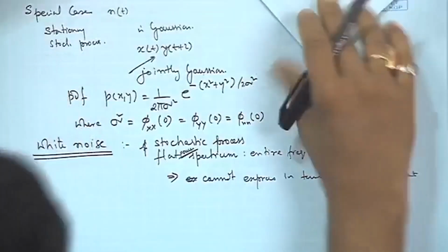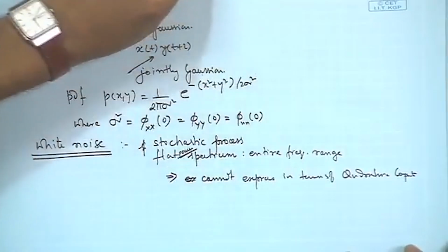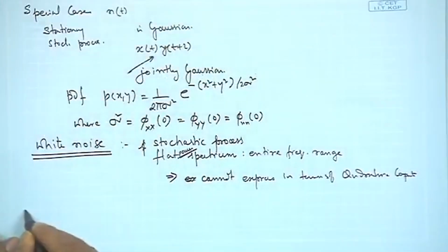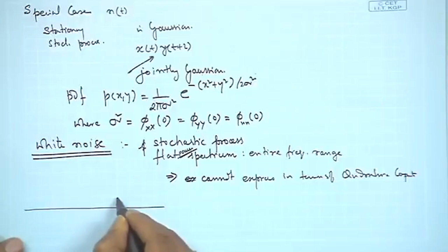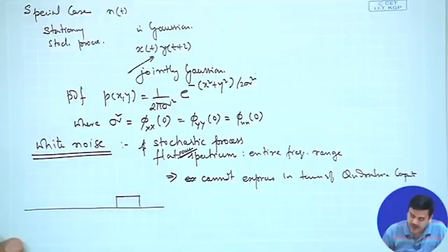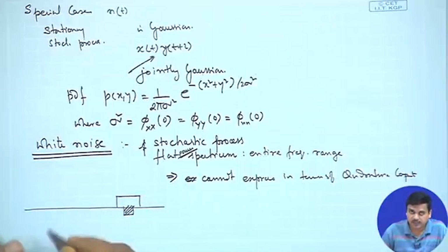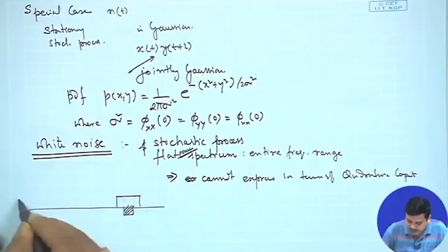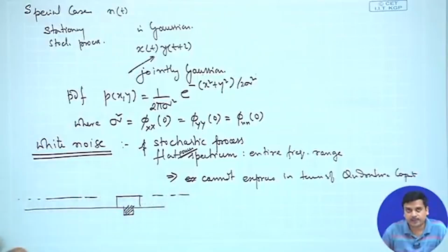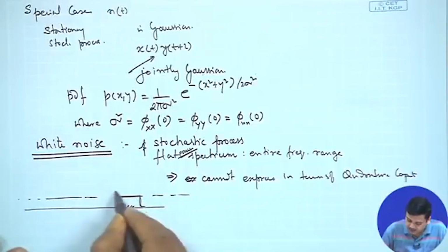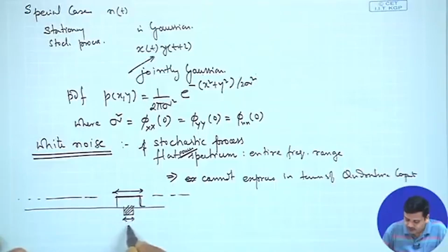However, in a typical communication system, your signal generally passes through a narrow band of frequencies, covering a band which is much smaller than the whole range, whereas originally the noise was across the whole range. If it passes through a band pass filter where the width of the filter is much wider than the width of the signal, then we have white noise over the band of the signal.